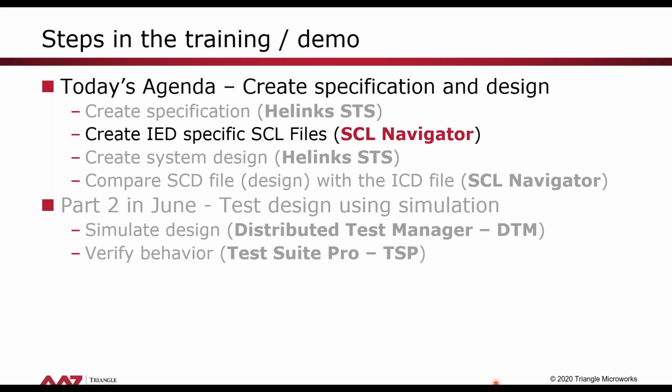How can logical node XCBR represent all the properties of breakers if only 2 on-off status and commands are connected to the IED? Can you repeat, if only 2 on-off status? Well, the logical node XCBR basically can represent as much as is wired to the IED. The minimum is typically the position, so the contacts for open and for closed that are wired.